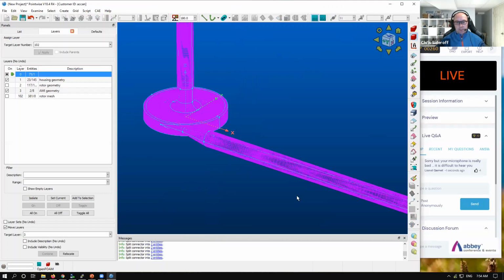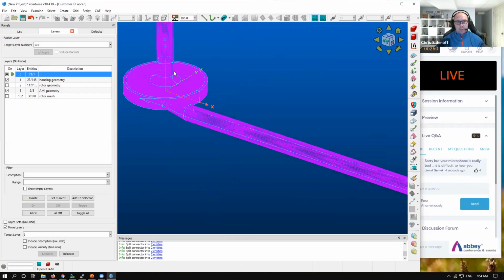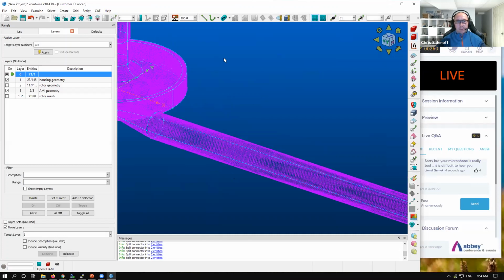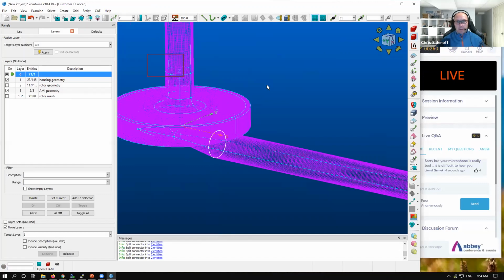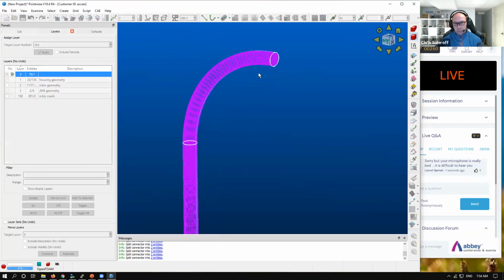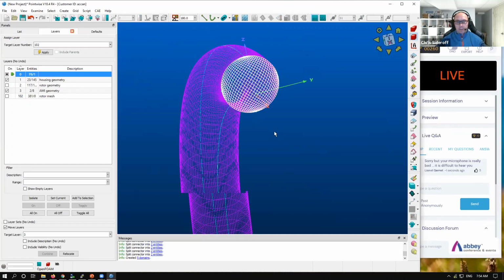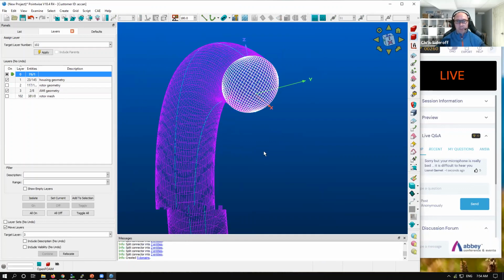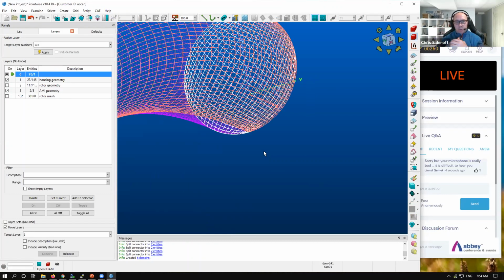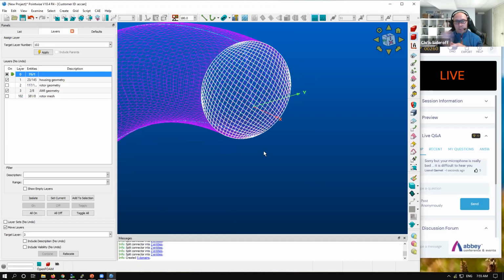Now I can select these groups of 4 connectors. Select these, and it's going to create the structured domain. Now you can see right here we have a structured domain, but this is not what we'd like. The character of the mesh is such that it's going to be really hard to pack the mesh near the walls. Anyway, the short story is that if this is a single block approach, we want to move to a multi-block approach.